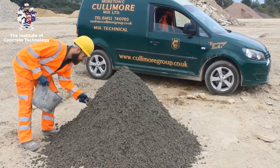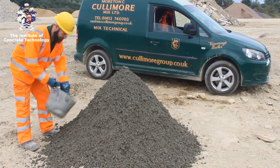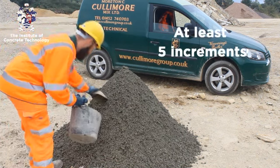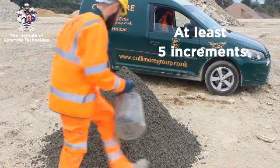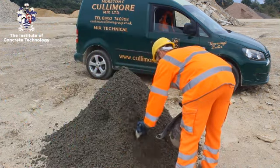Sometimes it is necessary to obtain a sample from a heap of concrete. In such a case, it is necessary to take increments from at least 5 different places, at varying depths of the heap.